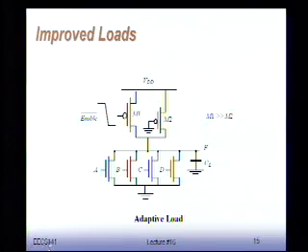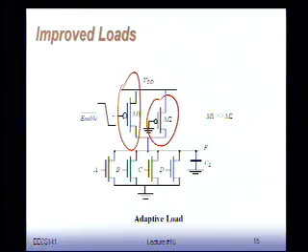So it's a trade-off. One argument says, why not combine the best of both worlds? Why not have both, a small PMOS and a large PMOS, and put them in parallel? When I do a transition, when the logic is switching, I enable that PMOS. Very small resistance, we're going to be fast, things are going to switch quite rapidly.